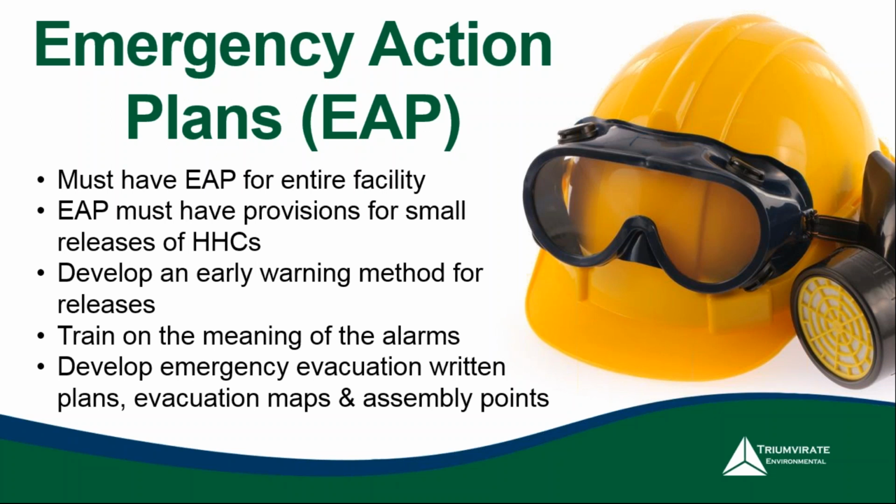And your emergency action plan here is going to get a little more beefy than a typical one would be if you were not in the PSM program, because you have to have it for the whole facility. It's got to have the provisions in here if you had any small releases of the highly hazardous chemicals, that's what HHC means, that we talked about earlier.